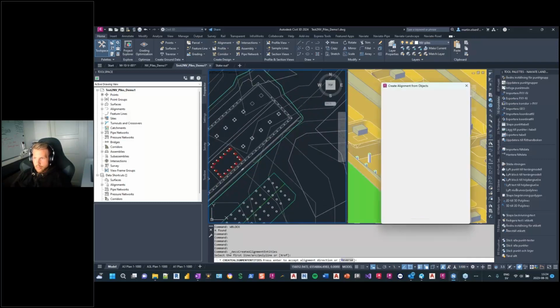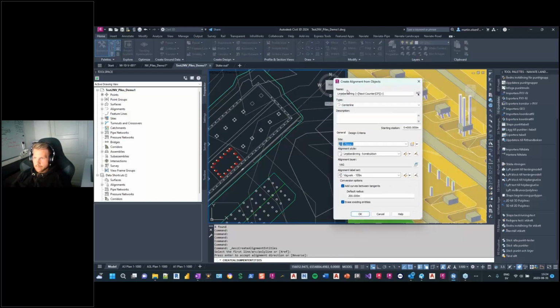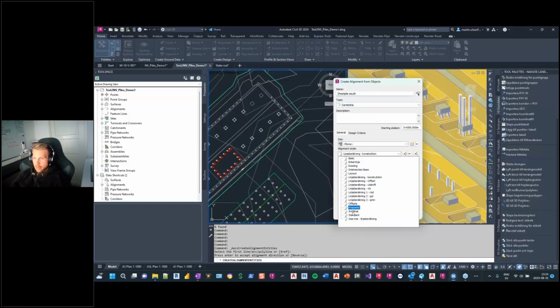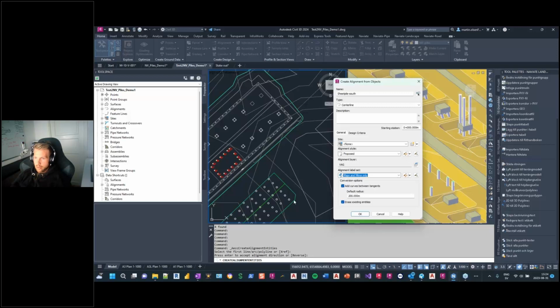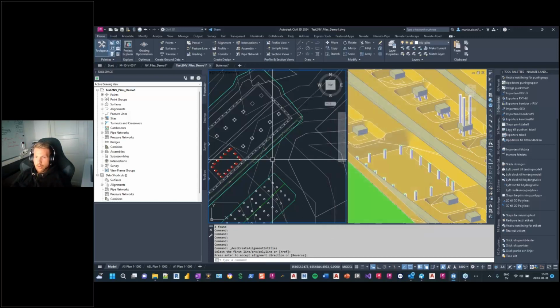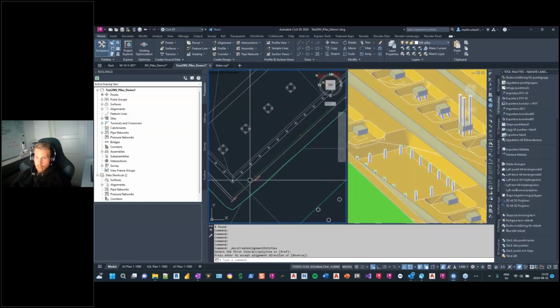with that direction. And then I can call this sheet pile south. Type centerline will work. Alignment style, choose this proposed. Labels, I'll just use this major and minor labels. And I don't have any radius or curves, so it doesn't matter, but I can uncheck this box and then press OK to create my alignment.